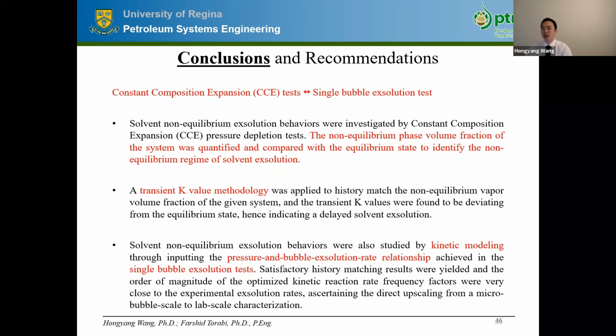Also, a transient K-value methodology can be used to history match the non-equilibrium vapor volume fraction of a thermodynamic system undergoing pressure depletion tests. And also we have conducted the kinetic-based modeling by inputting the pressure and bubble exsolution rate relationship achieved in the single bubble exsolution tests in a continuum-scale reservoir simulator, and we have achieved pretty good history matching results.